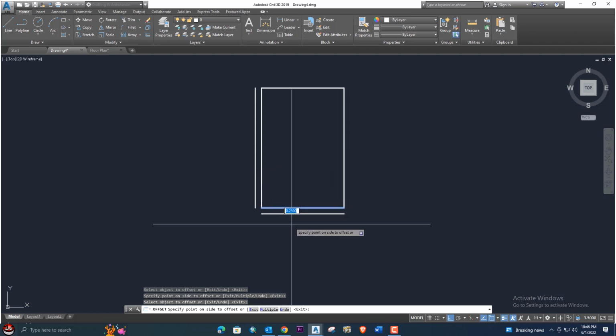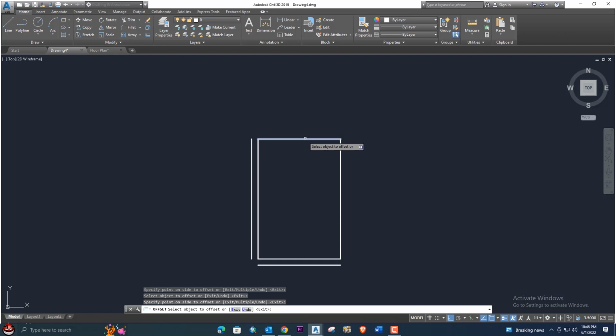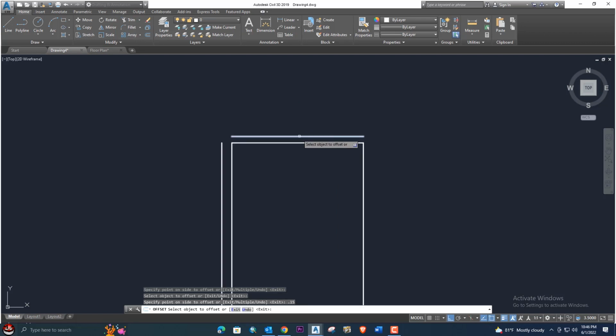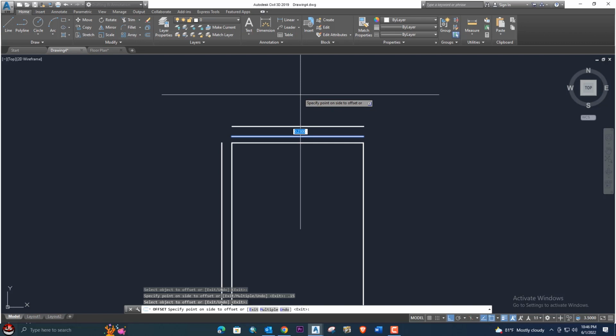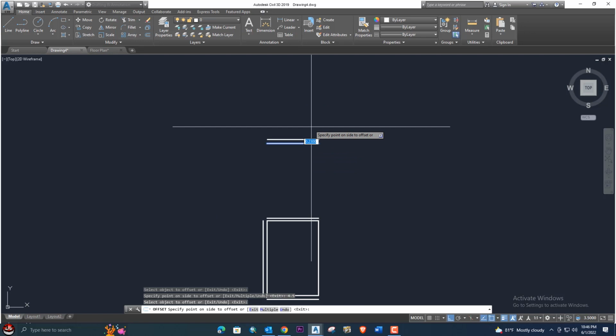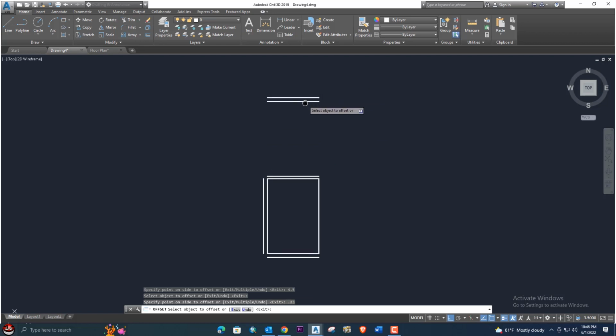Also click here. This is also an external wall, and here I am going to enter the internal wall, but I will change the distance to 0.15 and enter. Then again I am going to provide 4.5 meters. This one is the vertical distance. I will show it 4.5, and here I am going to give again the external wall. External wall thickness is 0.23. So you can see here.